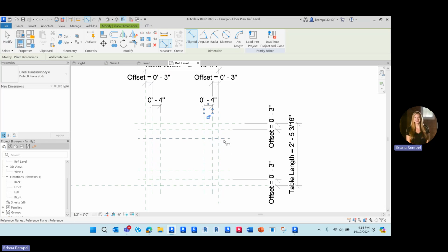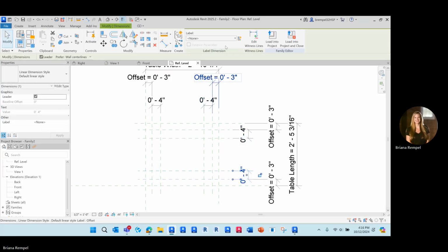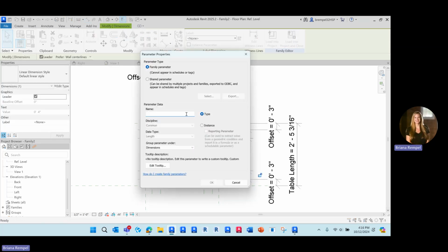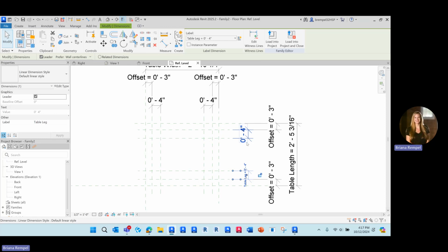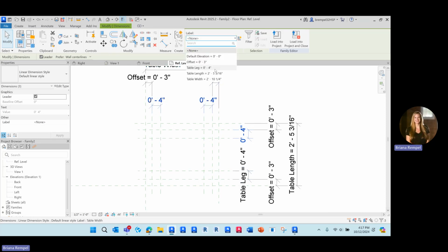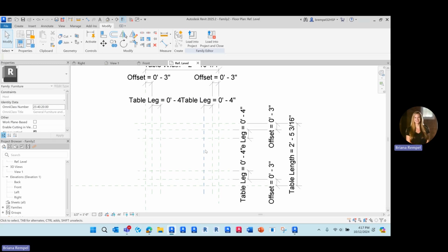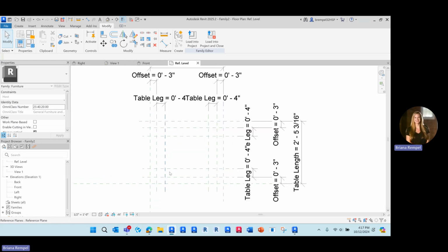That's going to over constrain the sketch here and here. So I'm going to go ahead and create a parameter for that. And then now that is created, I'll select these other 3, holding down Control to do that, and I'll apply the same parameter. All right, so now we've got this built in here for the X and the Y.